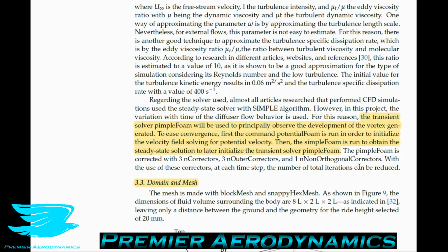But to initialize the case, they say first the command potentialFoam is run in order to initialize the velocity field, solving for potential velocity. So this is one of the most basic setups you can have, so that it's potential flow. It doesn't have viscosity. So this is good from the point of view that it makes the solution converge much quicker.